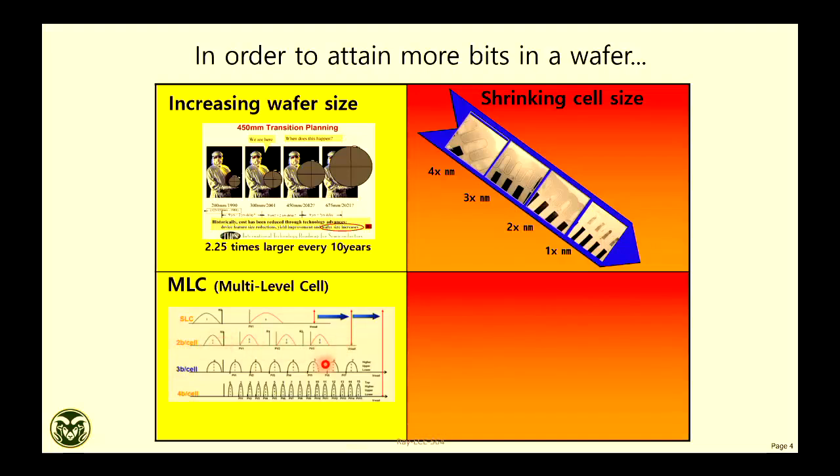The distribution is just to show you the statistics. In a memory row, or in a memory word line, you will have thousands of cells. You target the lowest threshold voltage to be, say, 0. But some cells can have a little bit higher threshold voltage, some cells a little bit lower. The next threshold voltage should be, say, 2 volt. But some cells can have 1.5 volt, some cells can have 2.5 volt. So that's why you need to keep some gap between different threshold voltage levels, and that's how you can reliably detect which threshold voltage bin they are in. Accordingly, you can say this cell is storing 0, 1, or this cell is storing 1, 1. So 2 bits per cell. That's the concept of logical scaling.